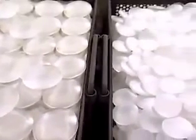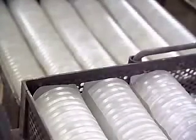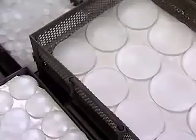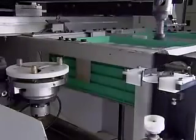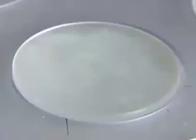Due to resultant press marks on its surface, it is still not possible to focus images through the pressed lens after annealing. To remove these marks and to make the surface smooth, the lens is polished during the following lens machining process. Using a curve generator, a super high-speed machine equipped with an artificial diamond grindstone, the surface of the pressed glass is ground until it becomes a curved surface with specified roughness and dimensions.